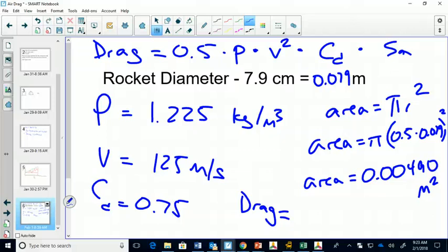The meter squared is just a unit. Velocity up there is a squared on the formula. Yeah. Somebody have a number? 35.17. I'm looking for some confirmation. Yeah? 35.17? Okay. My question to you is this. What units would this drag be in? Okay. Yeah, you're right. There's actually a simpler way we could say it, though. I'll give you a hint. It's kilograms times meters per second squared.